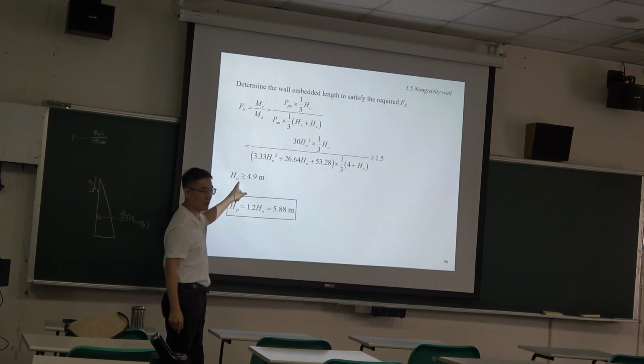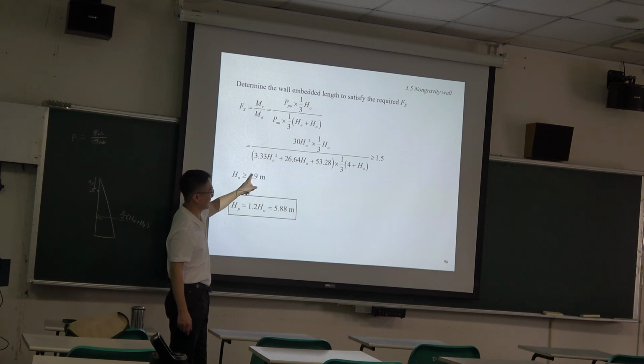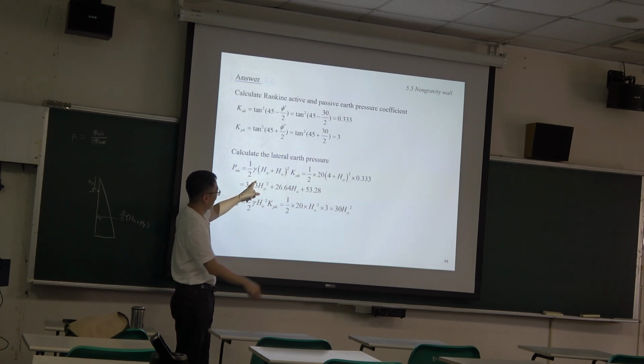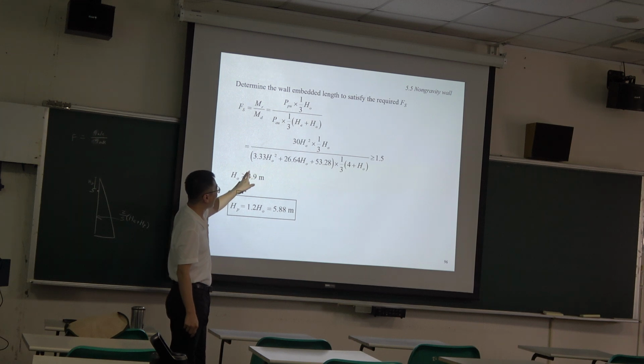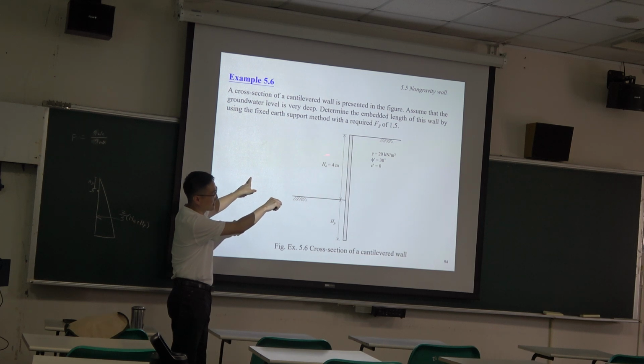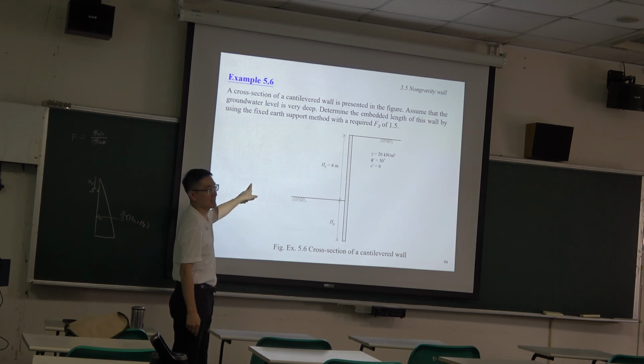So by trial and error, generally in sand, since it's a sand material, this value will be slightly bigger than the excavation depth. That's the experience.